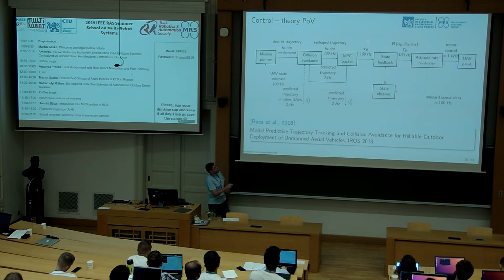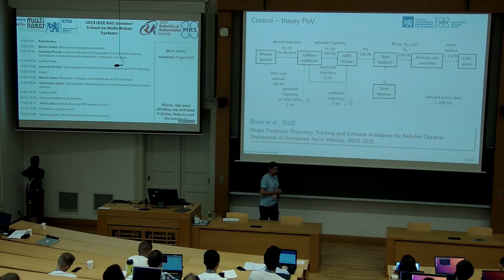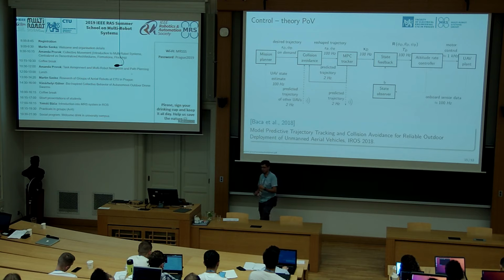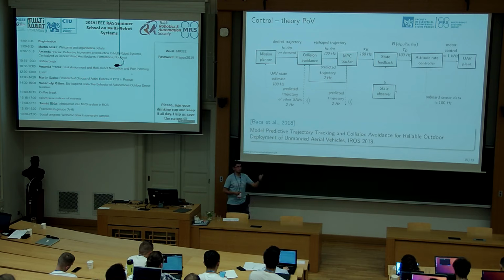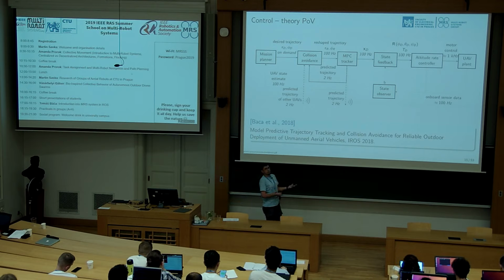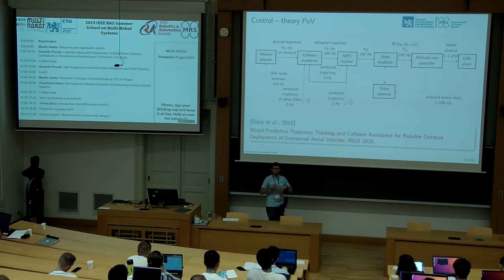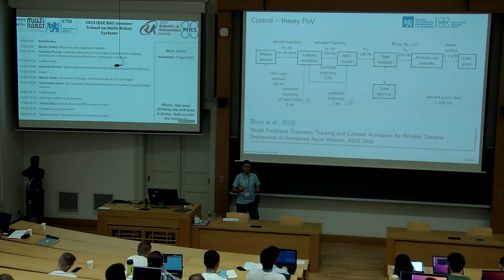Above that, we have something which we call a tracker. Again, we have multiple trackers nowadays. A tracker is a reference generator. It generates the desired position, velocity, and acceleration for the drone 100 times per second, so the controllers have something to do. The controllers don't know where to go and how to get there. They need somebody to tell them the actual path through the space.